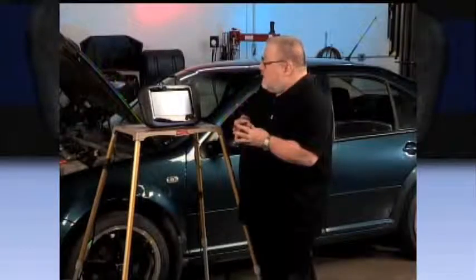We can also go ahead and log in to change adaptations. What login does for you is it gives you the ability to actually unlock the security system in various modules so you can go in and actually work on safety systems. A classic example of this would be the Mark 60 ESP ABS system. With ESP, you have a device called a steering angle sensor, and to actually do any work on that steering angle sensor, you have to log in and unlock that capability. So login ECU allows you to go in, enter the proper code, which happens to be 40168, and that allows you now to operate or to do basic settings or reset or testing on that steering angle sensor. So once again, important to have that capability.